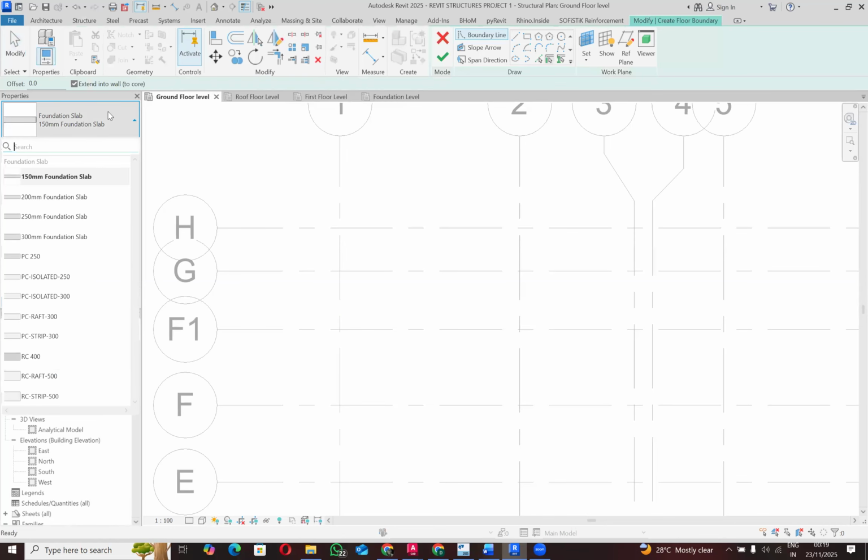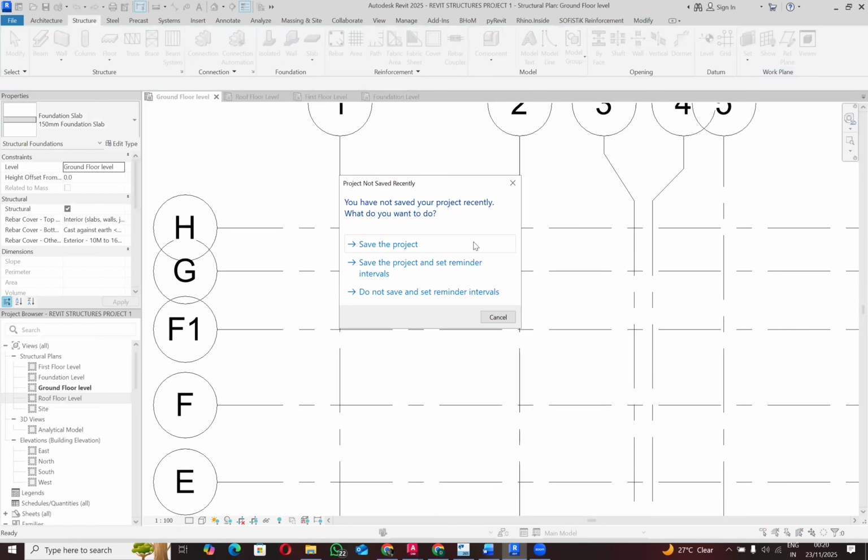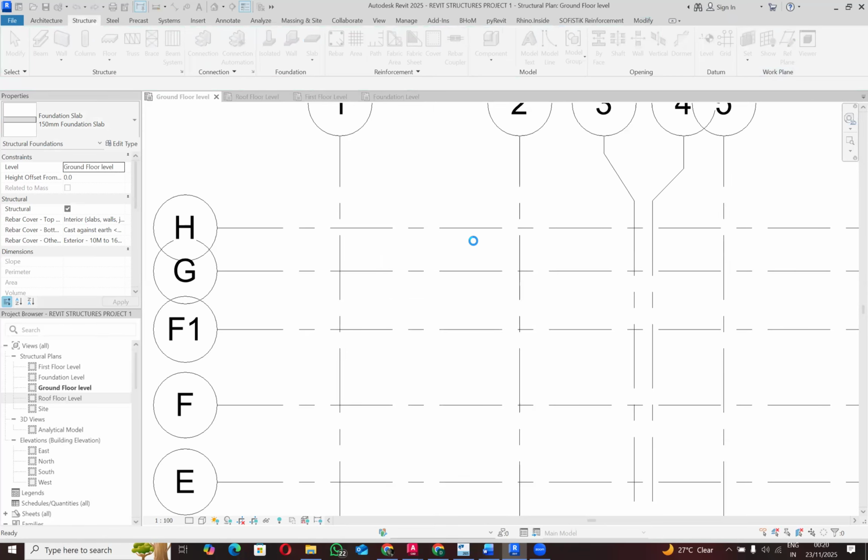We're going to use one of them. So anything slab related, strip, everything slab related for foundation, ground floor, strips, footing, we use the foundation area, right? So this we're going to come, we need to model before the foundation. Okay, let me save the project. Saving a project is important.